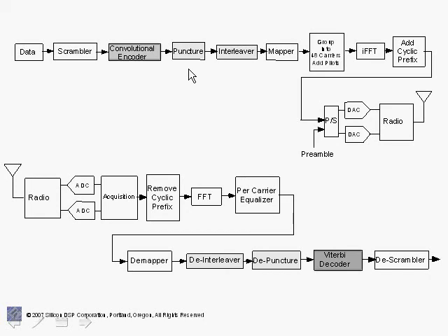We will talk about puncturing, which allows us to achieve high throughput in cases where we have high signal-to-noise ratio by trading off redundancy for throughput. We will talk about the interleaver, which combined with forward error correction coding provides for a robust, reliable communication link over wireless communication channels with OFDM. There are many issues involved with OFDM, in particular the arrangement of the data carriers, the pilots, the guard intervals, and we'll talk about that.